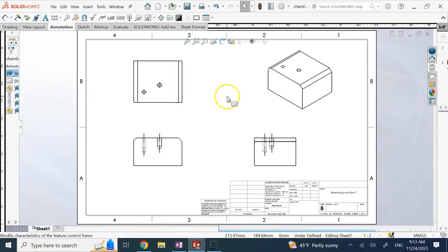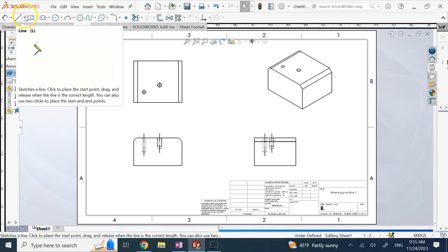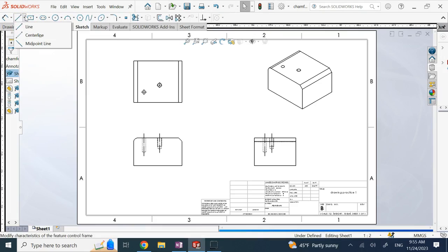So whenever you see this dash line and a dimension in addition to a datum symbol, that means a partial datum. So in SolidWorks, let's say you have something like that, and you want to use this bottom surface as datum A, but only a portion of it. First we need that dash dotted line for a portion of this. We need to insert that, give it some dimension, and then add this datum symbol. So in order to insert the dash dotted line, we go to the sketch, and see if we can add a dash dotted line here.